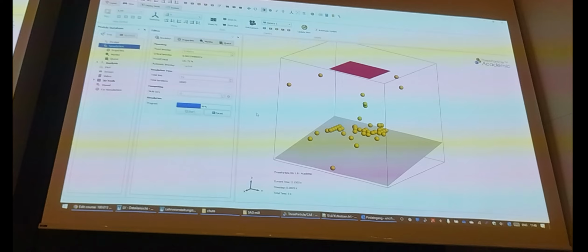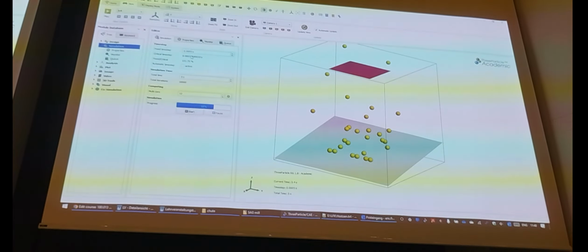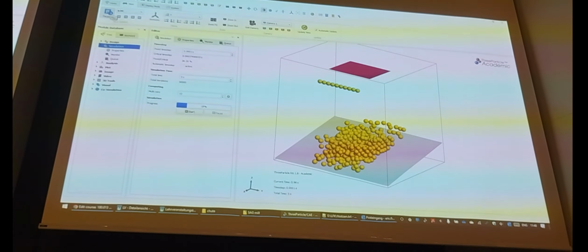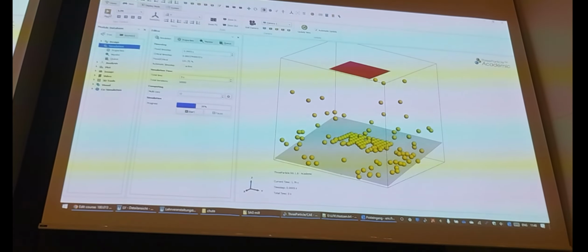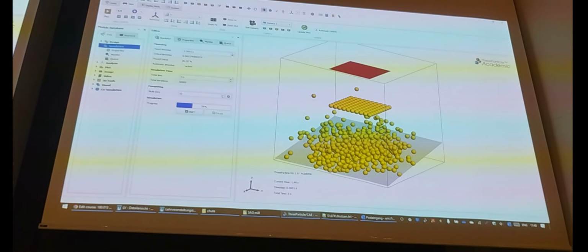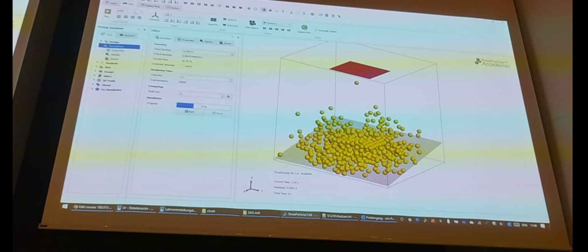This would be a supercritical simulation. Time step is much too big. If anything like that occurs on your system, your time step is too big. You go back to where the instability occurred. You see, at first it was stable, and at some point it went unstable, where I changed the time step. That is a stable time step. So as long as the simulation stays like that, it's okay. As soon as the particles explode, poof, everything goes apart. Simulation is super stable.